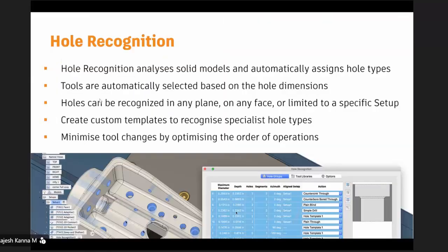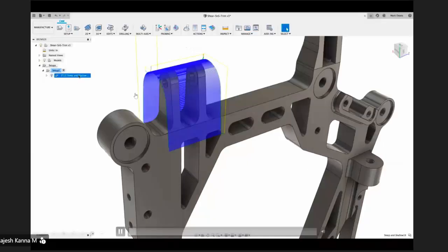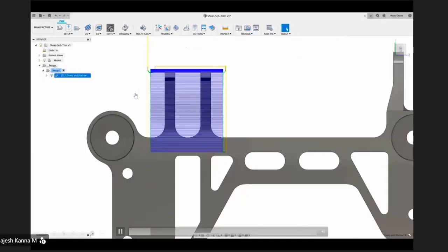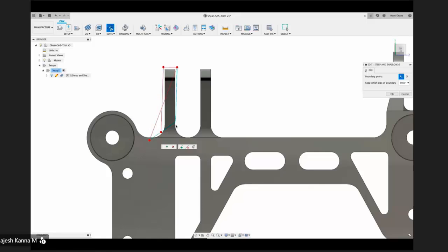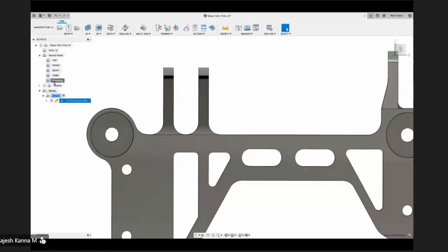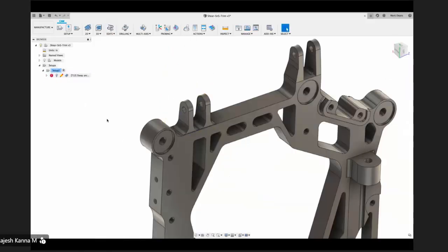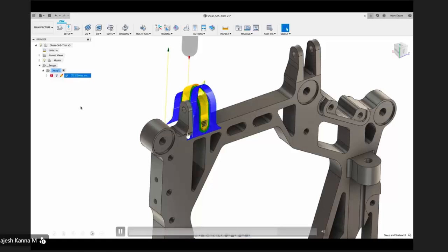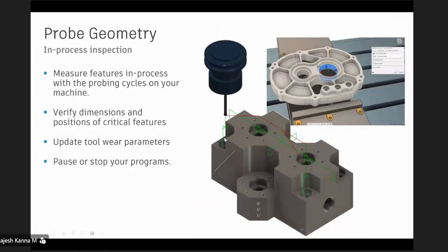And we also have toolpath modifications actually. So what is meant by toolpath modification? Sometimes the toolpath we created is unnecessarily moving in the air actually. So for that, what we can do is trim the toolpath wherever it is necessary, right? So you can see that it is getting trimmed actually. So that is also a useful feature for you.